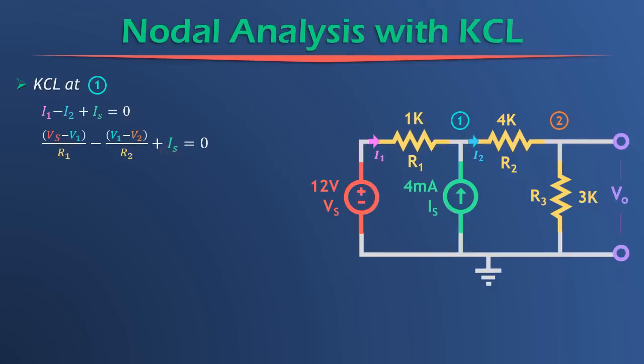And now we can do some algebraic, clever rearranging, and we can get it into a form like this, where we have V1 times some constant plus V2 times some constant. And usually these constants are the R constants for resistance. And then we're going to set that equal to the other constants that we know here. Alright, so just let that be for now. We have an equation with two variables. So in order to solve for both of those variables, we're going to need another equation so that we get two equations, two variables, and then solve using some method.